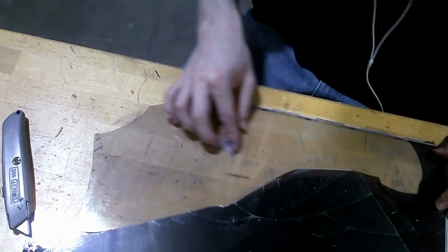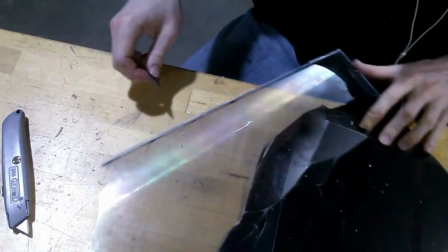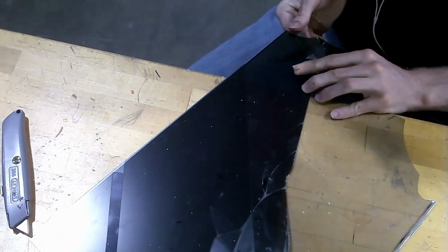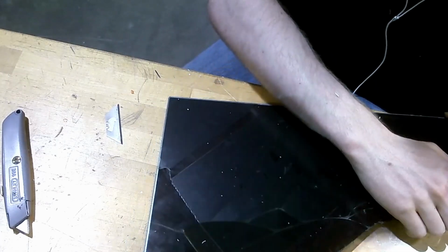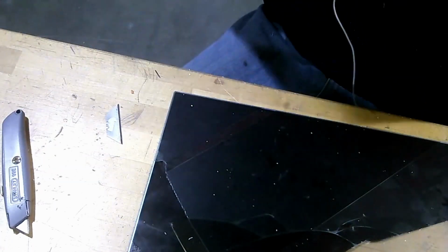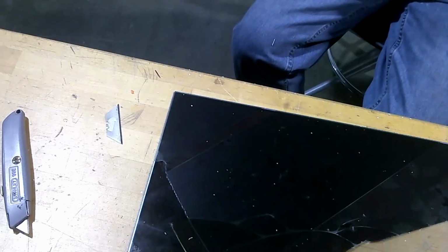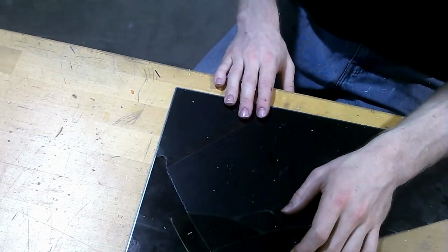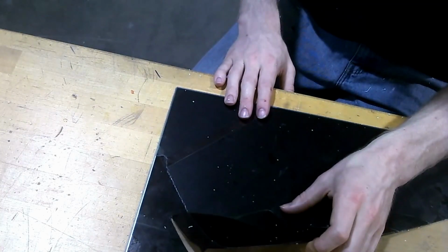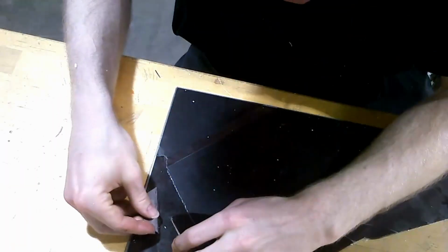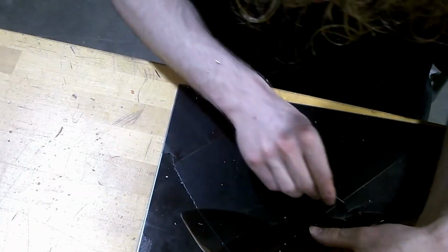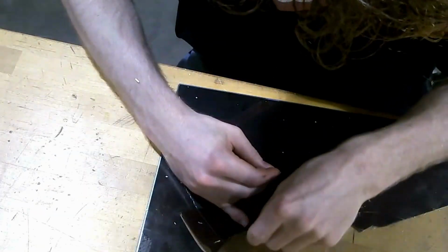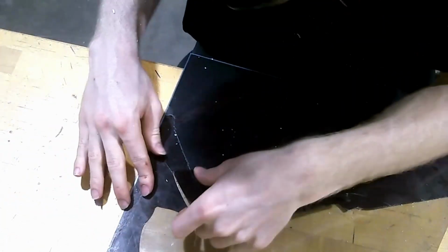Additionally, as that film layer is removed, the glass is very prone to breaking, and you want to pull on that film as parallel to the glass as possible to prevent as much force in the perpendicular direction to the glass as possible, because that is what's really going to break it, if you try to pull up on that film as you're pulling it away from the glass. That is what led to a lot of the breakage over the course of this project.